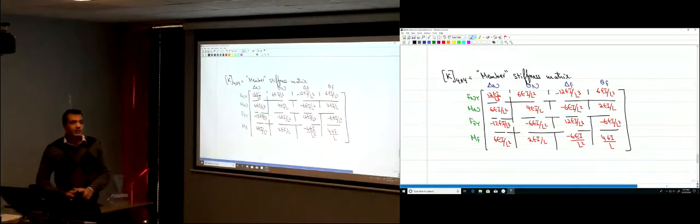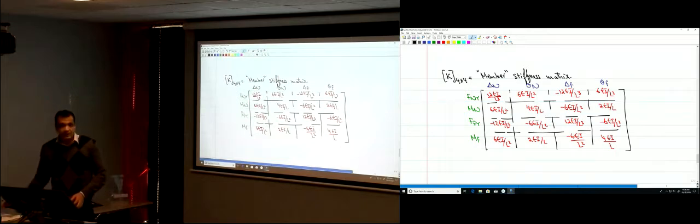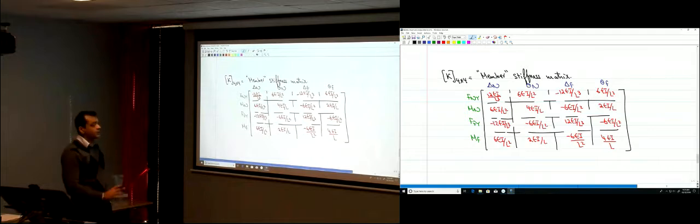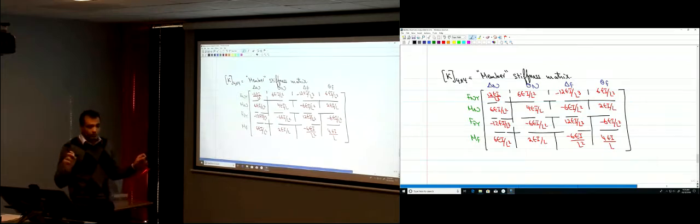So now, this is called the member stiffness matrix. When we derived this, we just had one member with two nodes, a start or near end, and an end or far end of that member. As we see here, when we derived this matrix, we had EI as a general number, L is general, so this applies to any beam member. So this stiffness matrix is constant for any prismatic beam element.